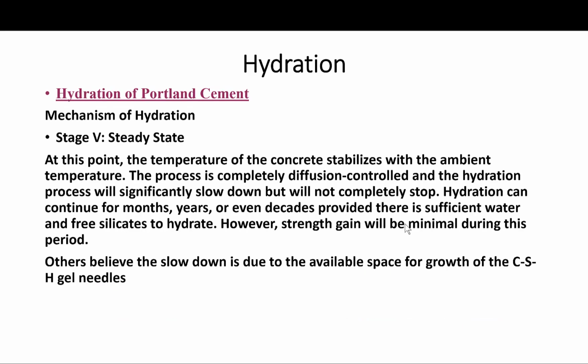Okay, then we have stage 5, or referred to as the steady state. At this point, the temperature of the concrete stabilizes with the ambient temperature. The process is completely diffusion controlled. The hydration process will significantly slow down, but will not completely stop, as long as there is water. That's why curing is important, guys.